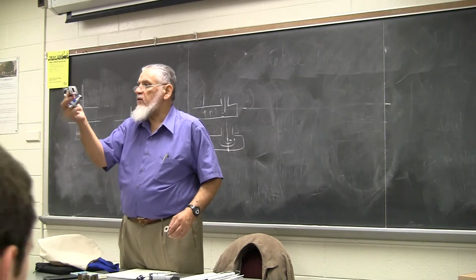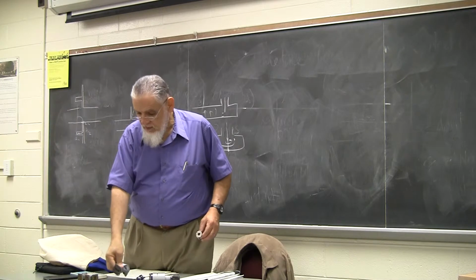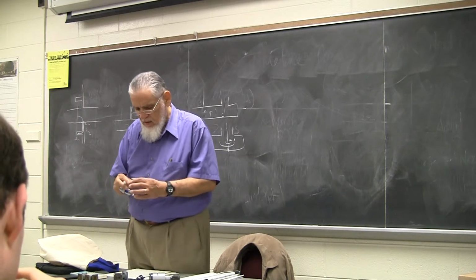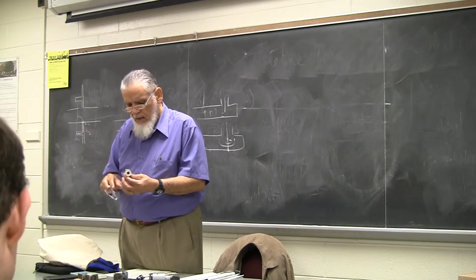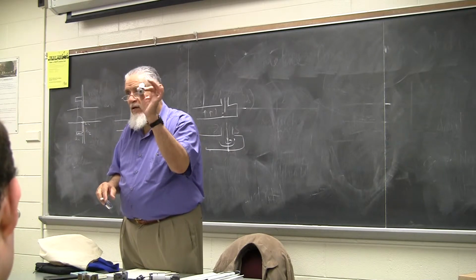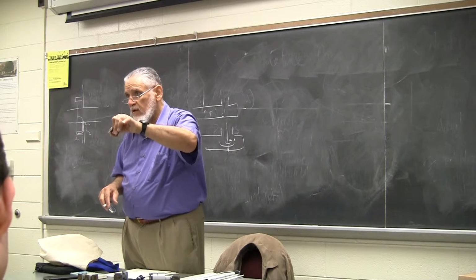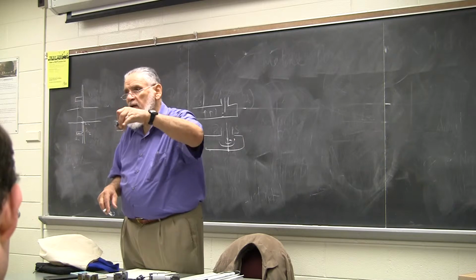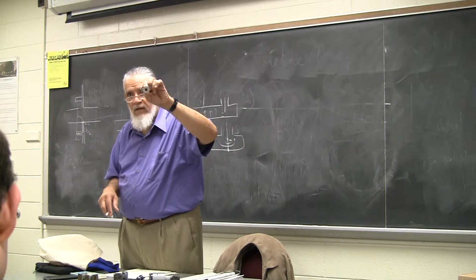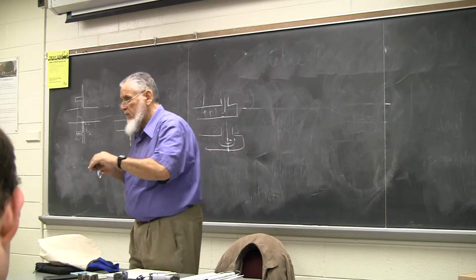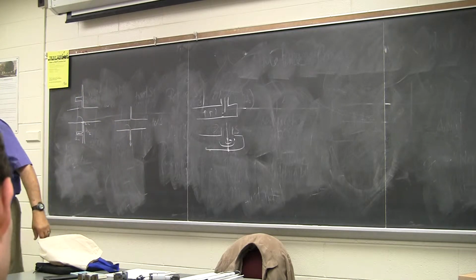There's another bend that's not exactly 90 degrees, I guess. We have the 90 degree one. This one here is a coupler between a rectangular and a circular guide, right? And the circular guide actually also has a mode filter inside. So, very interesting situation.